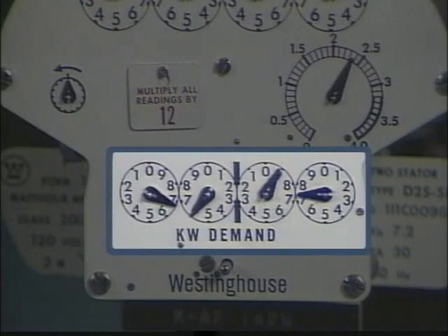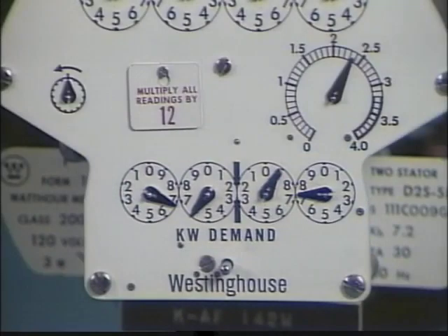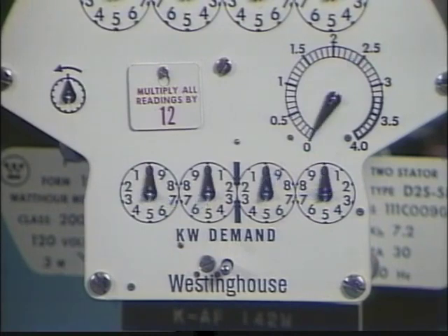These 4 dials indicate the sum of the maximum demands from previous billing periods. They're similar to the 3 dials on a dial register. However, here, they indicate the cumulative demand over numerous billing periods. This is how the cumulative demand dials work. When the cumulative demand register is first put into service, all the demand dials start at 0. The test dial moves upscale to indicate the maximum demand over the block intervals for a billing period.